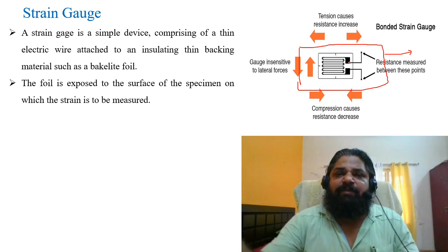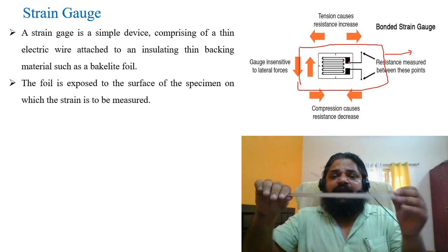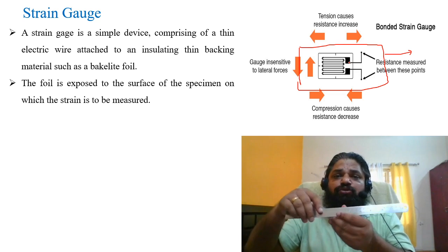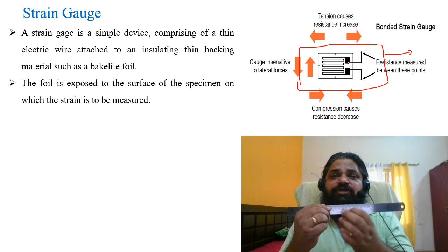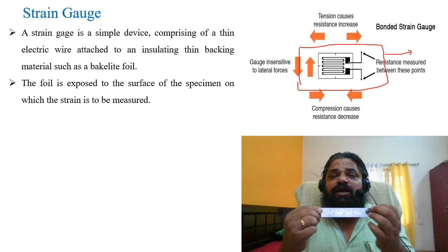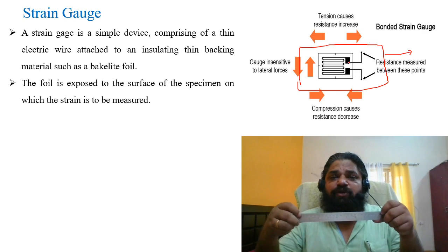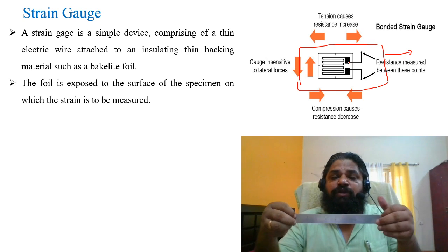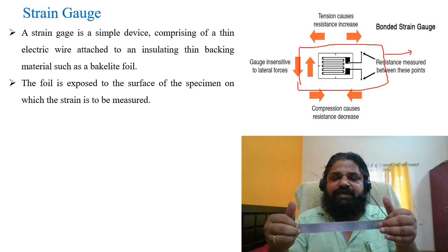Let us say I have a rectangular rod under tension and I want to measure the strain. I will glue a similar one-element strain gauge at some place. In testing, we put two gauge points, and between the points we have the gauge length, which we discussed during the stress-strain diagram.